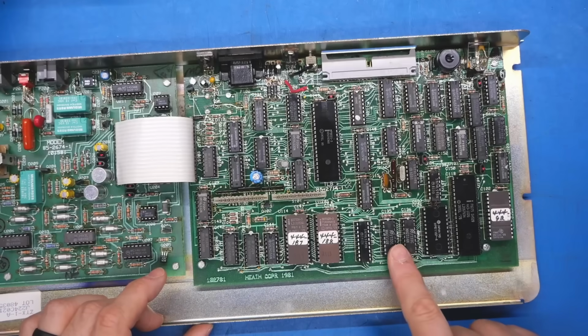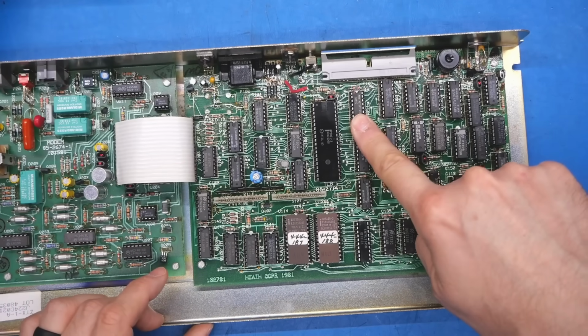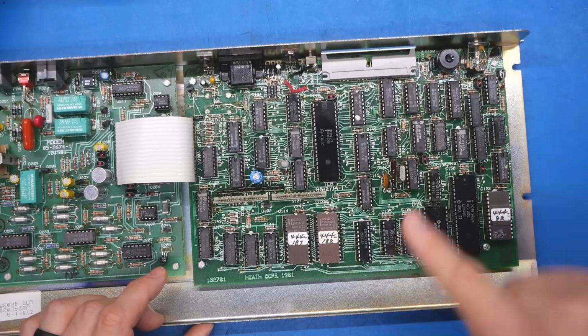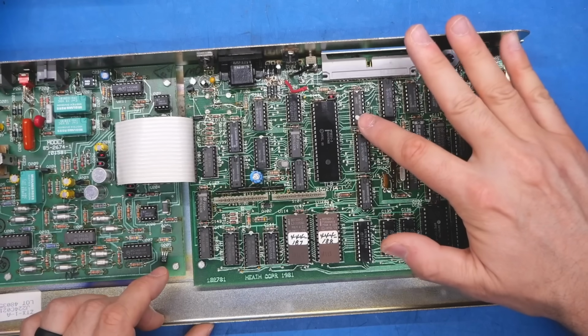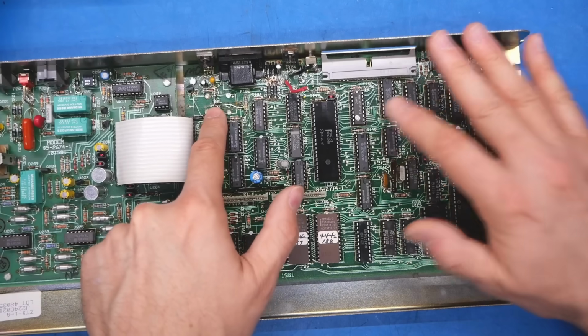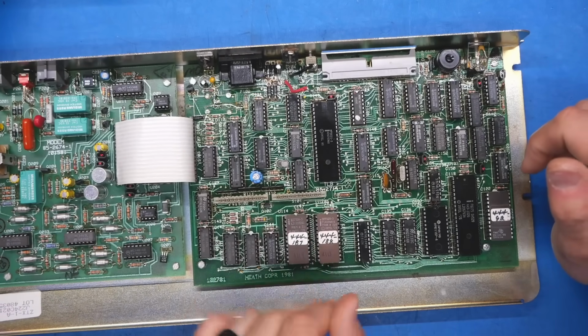Now, I have to wonder why they're using 2114s down here, and they're not just using a normal label 2114 up here. They're using this NEC part. So why are these different part numbers? These are National Semiconductor. I kind of think it might be because this might be lower power. Like it can run on a 1.2 volt NiCad, while these might not be able to maintain their memory storage at such a low voltage.